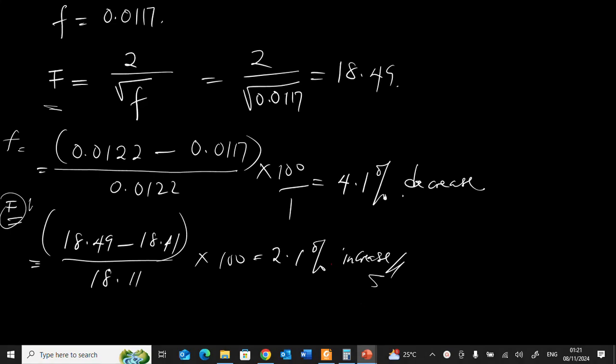The third part of this video is calculating the outlet pressure when given the inlet pressure. Now, we are going to use the general flow equation to solve this particular problem. But before we do that, we need to calculate the compressibility factor. The compressibility factor is not given, and we are going to use the CNGA method to calculate the compressibility factor.